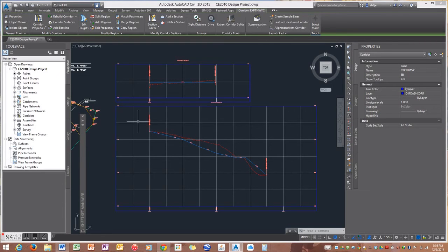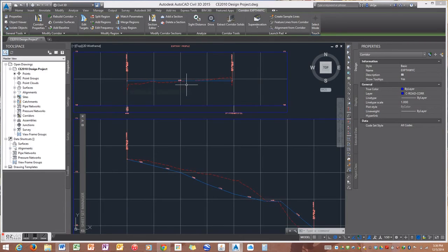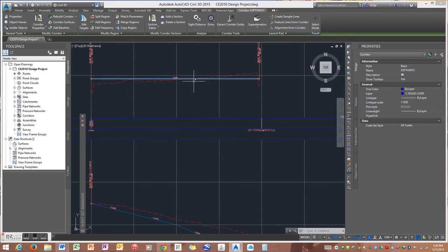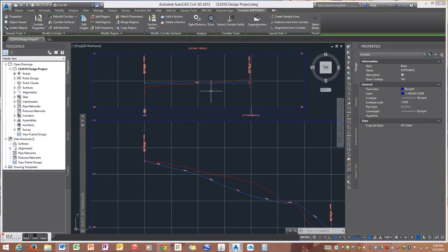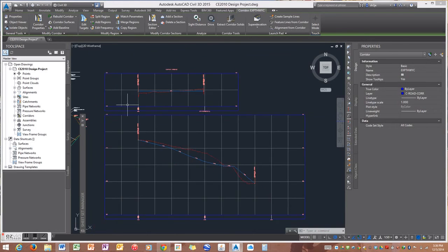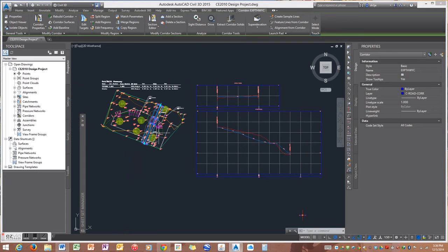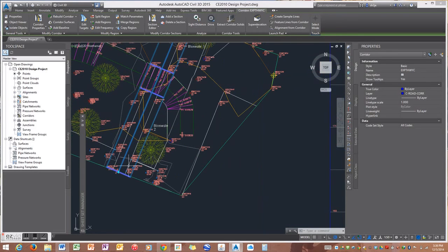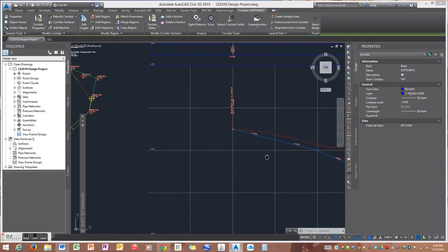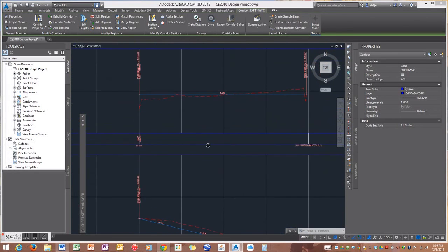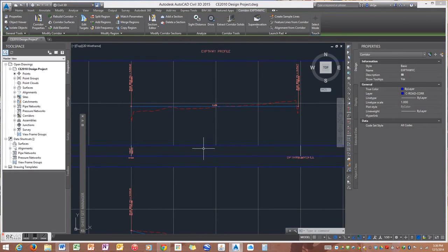This is the flattened existing pathway that was expanded by 15%. And again, this left side of the profile corresponds to the bottom section of this pathway. So as you can see, I've flattened that out as well to reduce the speed of the runoff from stormwater.